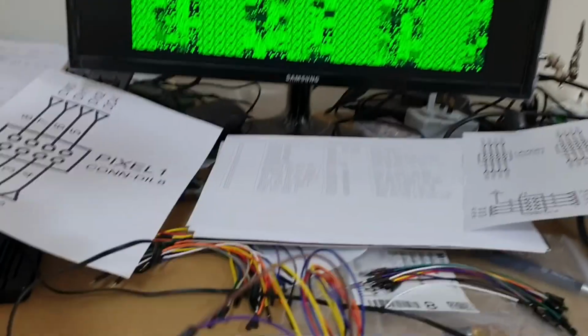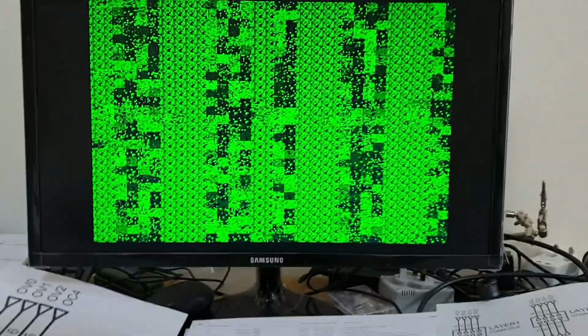If you notice the top left-hand character of the screen, I'll zoom in a little bit here, it's the same as the character which is output during contention, which indicates to me very strongly that it's 3FF in palette memory. Okay, the top 8x8 pixels do not change when I flip between contention screen and normal character screen.